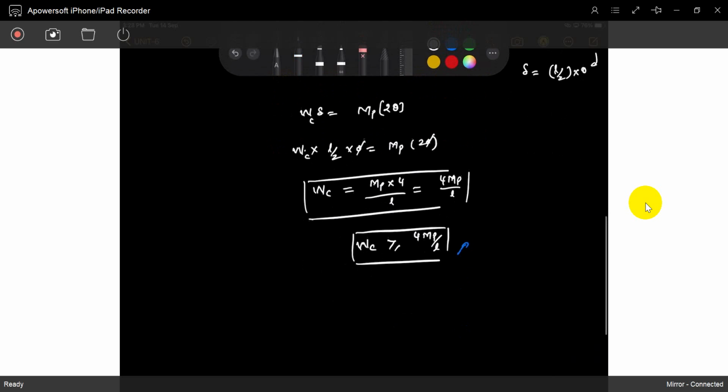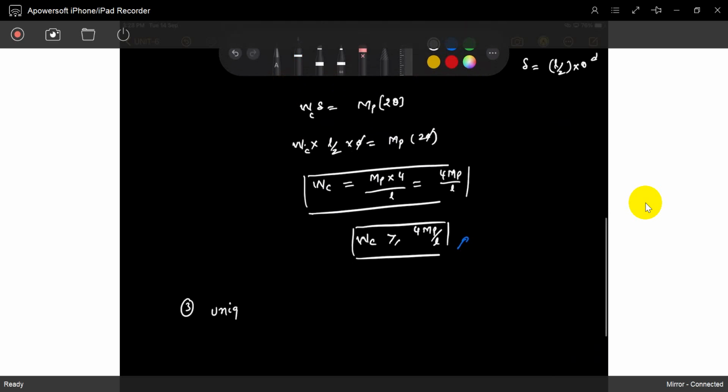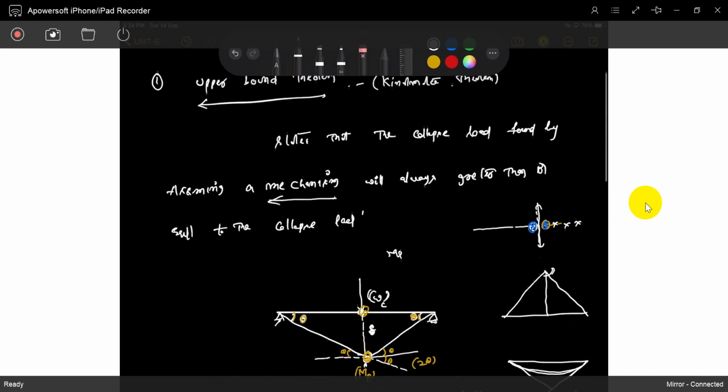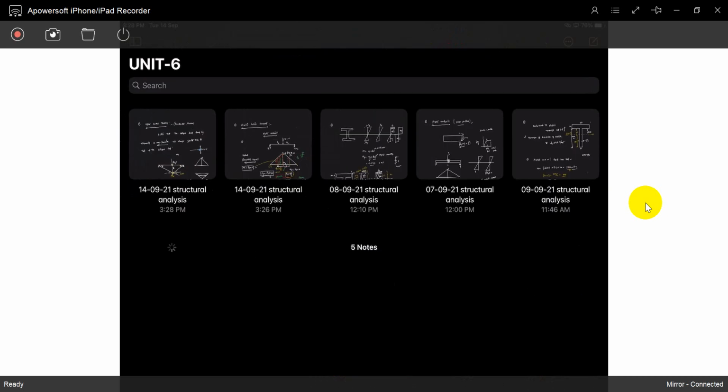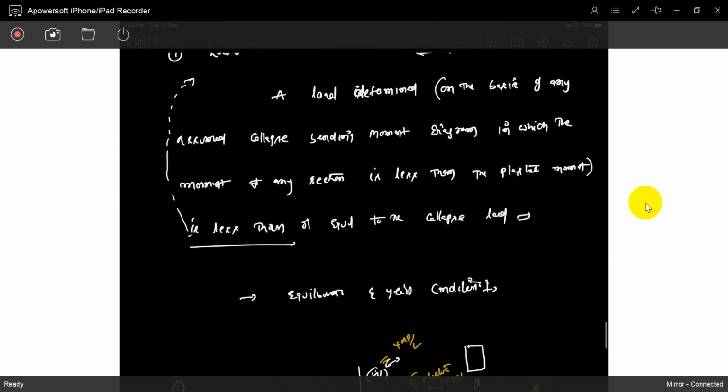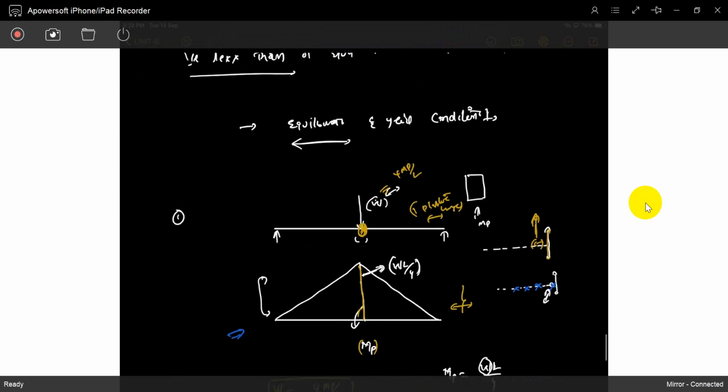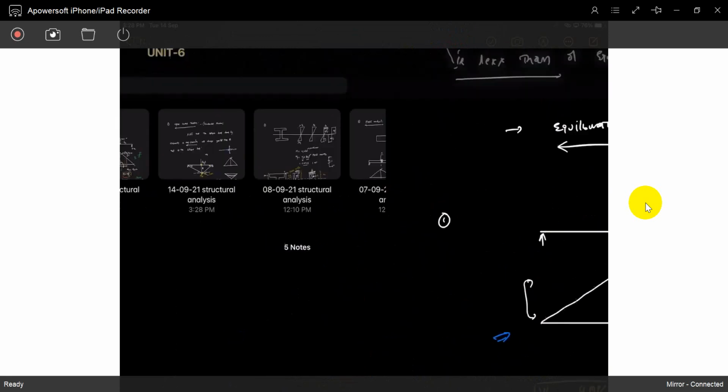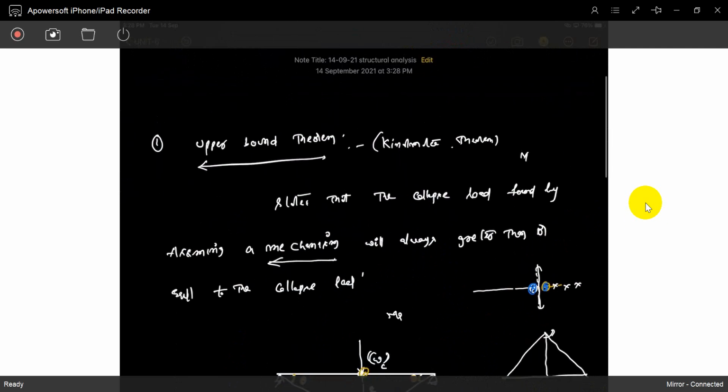There is no theorem. Uniqueness theorem. What is unique? Just consider those two values. If it is possible to arrive at a system of bending moments for the structure that satisfies equilibrium conditions, and a mechanism condition. Now you can see previously it considers equilibrium. These situations are considered. Now the kinematics considers mechanism conditions. Understood? Kinematics enters into the mechanism, not equilibrium situations.